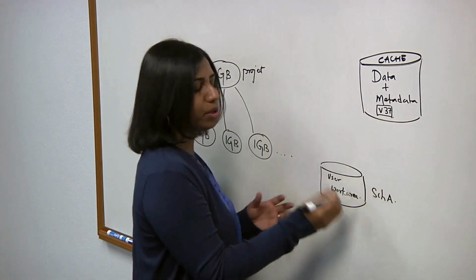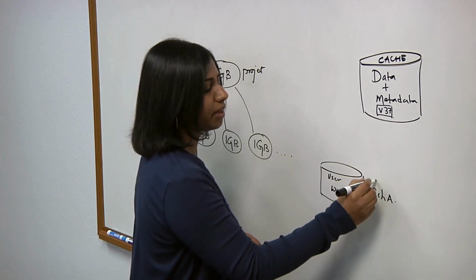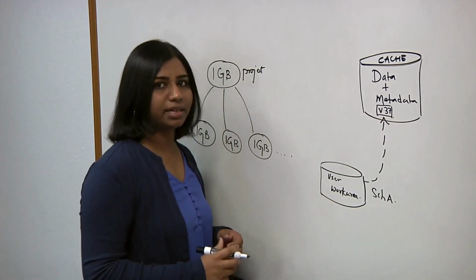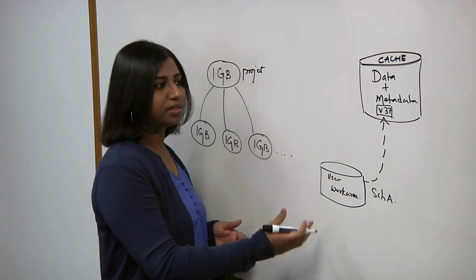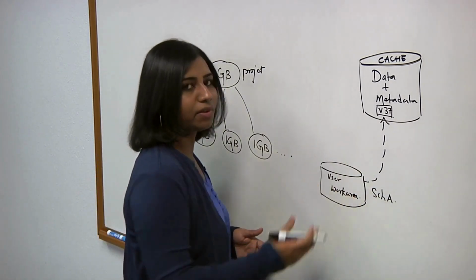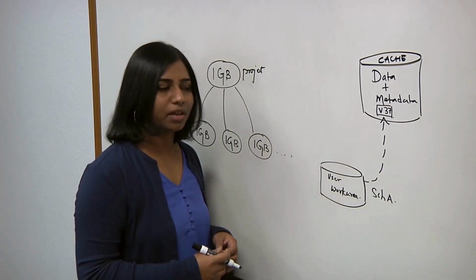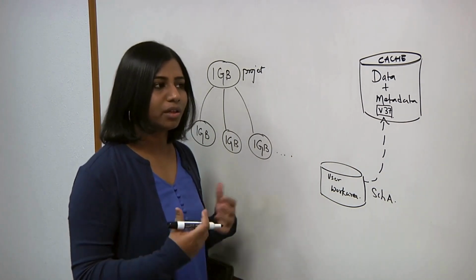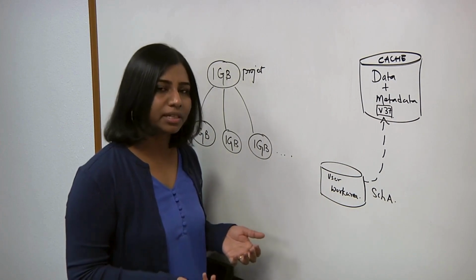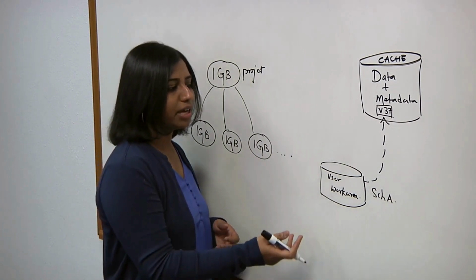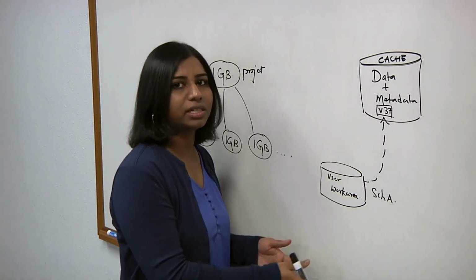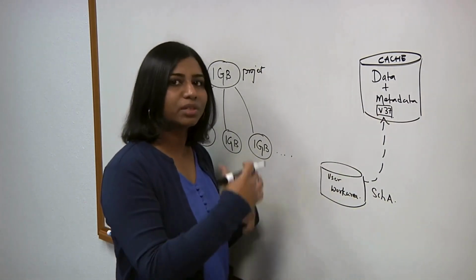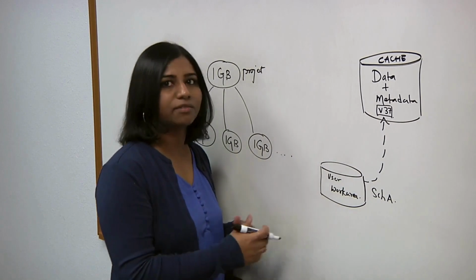Now, from your work area, you could simply have a symbolic link pointing to this real copy of the file inside the cache. Now, this is one version of one file in the project. You could have really large analog design libraries with a lot of schematics and a lot of layouts, and that's a lot of binary data. Now, imagine if you were to replace all of that data with just symbolic links pointing to the actual data in the cache. You're talking about reducing the disk space consumption to about tens of megabytes.